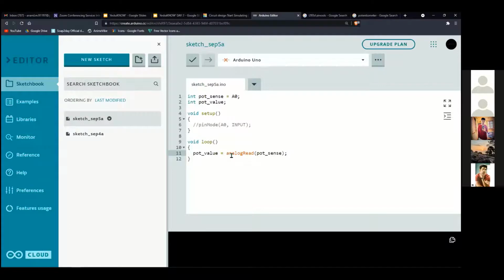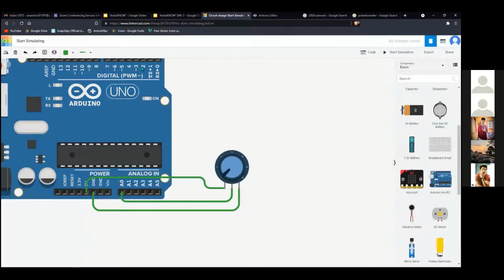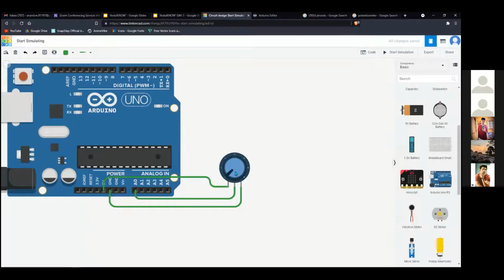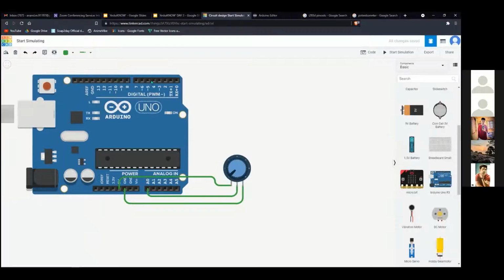So for this, there are multiple ways you can express it. For example, you can connect an LED to one of the GPIO pins, and you can specify in the code that once your potentiometer value rises above 1K, the LED should turn on. Or you can have a buzzer, and you can modify your code so that when your potentiometer value rises to a particular level, the buzzer will activate. So these are external components that need to be fitted with your controller in order to showcase this.